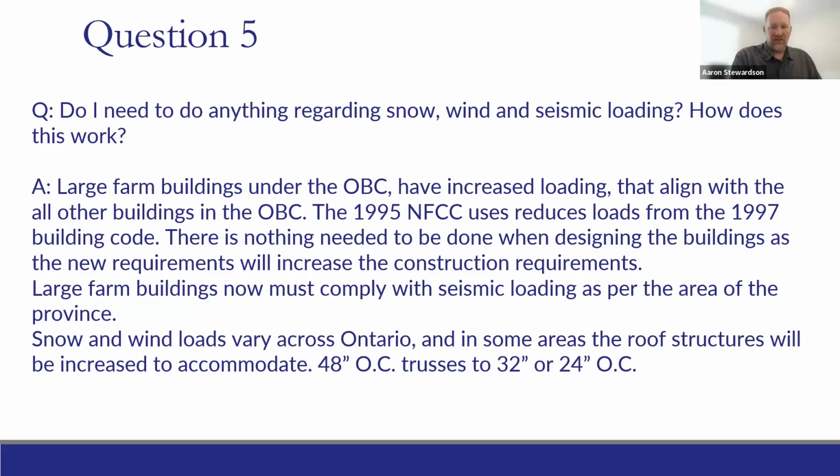Down in the southern part of Ontario here, Leamington, Windsor area where the snow loads are very low, there may be no change, right? I know up here in Huron County where the snow loads are increased, especially the proximity to the lake, we are seeing that the trusses are spaced closer together, and that generally accommodates that increase in snow load. But there's nothing you need to do for existing buildings. This is only for new large farm buildings.